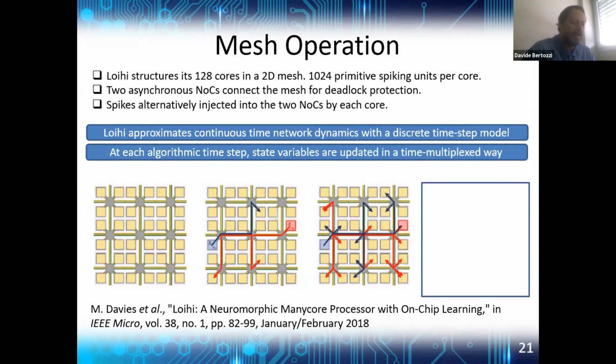I guess they are using algorithmic routing in the sense that they have some small hardware routing logic in every router. The network on chip itself only supports unicast distributions. So what happens when we have to spike to more than one neuron? In this case, we need multicast.